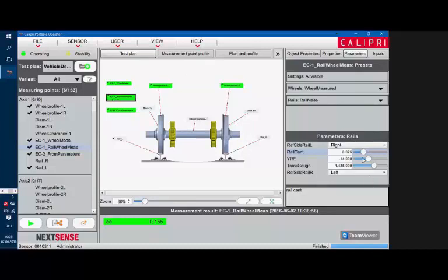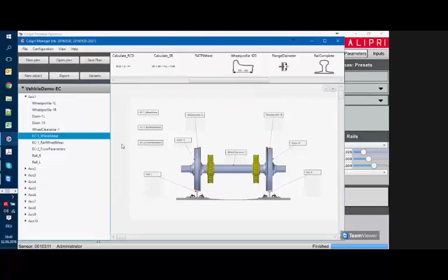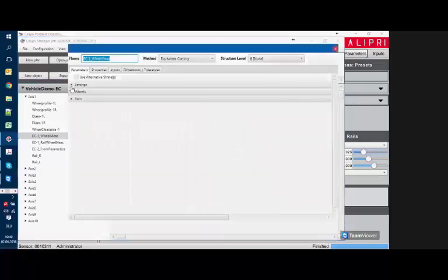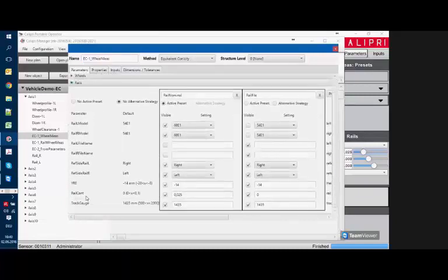In settings, under measurements, the precision is set to 3 digits or 4. So 2 digits are not sufficient. Yeah, you have to log in as administrator in the CPO to be able to set that. So that's just important for this rail count value because we need to define it in that way. And for 1 to 40, it leads to a value of 0.025. For 1 to 20, 2 digits would also be sufficient. In the Calipri Manager application, you don't need to define any amount of digits because you can write as many digits as you want, and these are stored as well. So if you just define the 1 to 40 value in the Calipri Manager application directly and you set this value to invisible, then it's also fine.